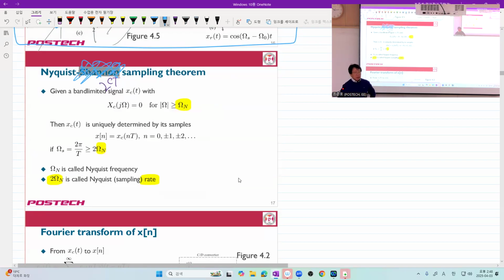The Nyquist sampling theorem is for finite energy deterministic signals. And Shannon extended the Nyquist theorem for strictly band-limited, finite power random processes. And after combining these two theorems, people call the theorem the Shannon-Nyquist sampling theorem or the Nyquist-Shannon sampling theorem.